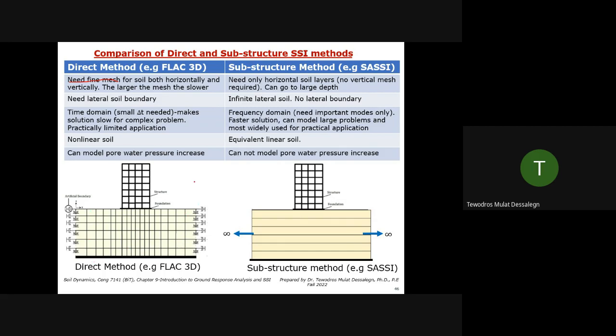And wherever you are stopping the model, you have to introduce damping, horizontal and vertical. At some point in the depths, like if you have bedrock, you may introduce springs with dampers, or somehow you should introduce damping for the dynamic case, so that the waves entering are absorbed.